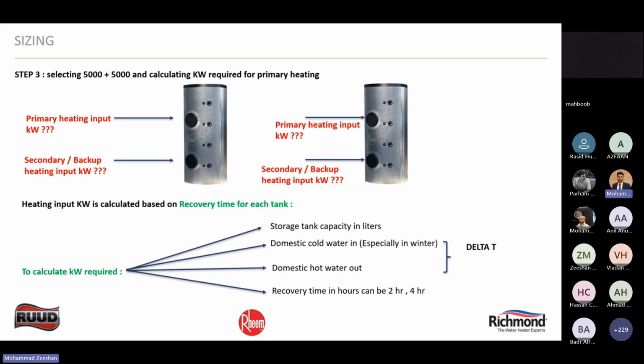Typically, between the first peak as well as the second peak, which is morning and the afternoon, there is a gap of at least 3 to 4 hours, which basically is your time to recover the hot water. So, depending on the number of peaks that you have, you will have to decide your recovery time. We do not recommend recovery times to go beyond 6 hours in commercial projects. But there are cases where we have designed it between 3, 4, and 6 hours, depending on the various site factors.